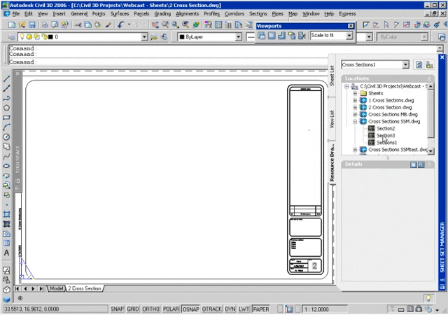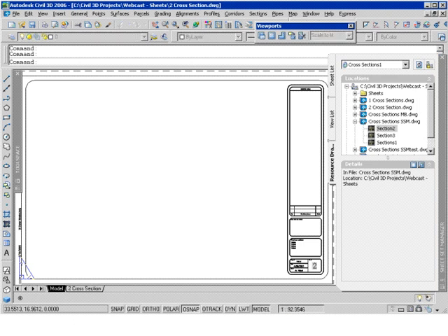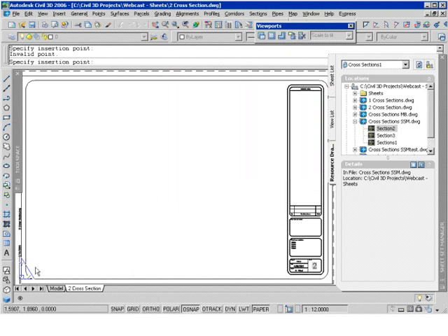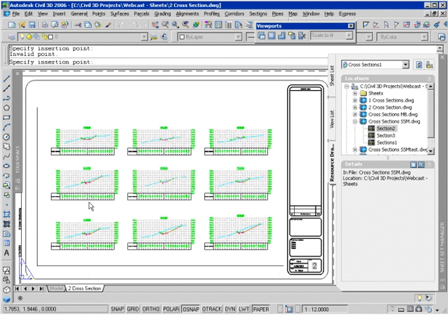Again, just back to our resource drawings, I'll drag in Sheet 2. And once it's in here, we'll right-click and set the scale again. 1:40, and then I'll just pick a point here, make sure we get it on our screen. And now that we have this done, we can take our sheet set, and I'll just wait for it to finish regenerating here.